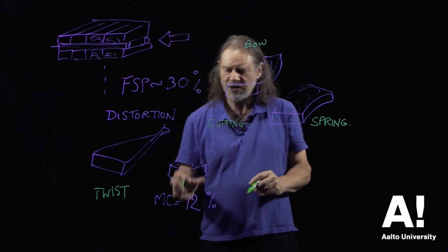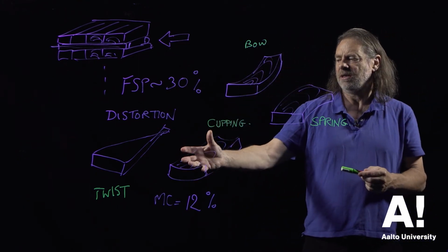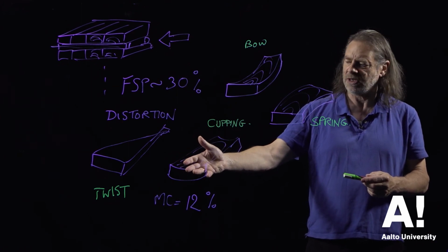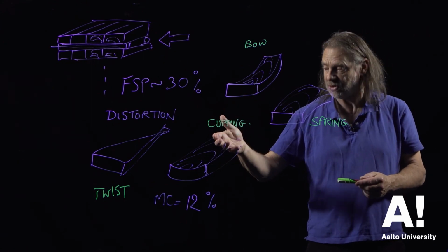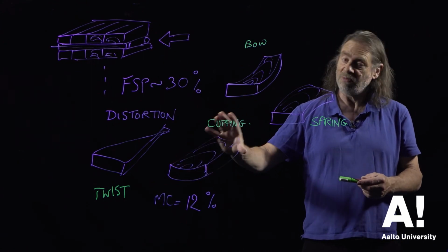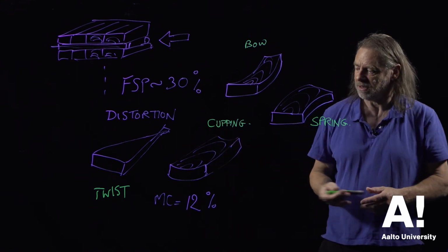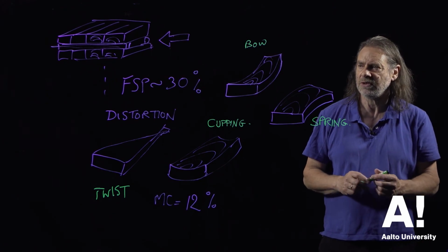Even if you dry the wood correctly and it doesn't display this in service, it may be that if it hasn't been dried to a low enough moisture content for internal use, or too low a moisture content for internal use, when that wood equilibrates to its internal environment, it may display cupping in service. We normally dry wood to about 12% for internal use.